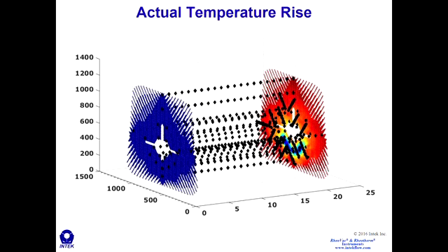And so there are other ways to monitor air binding as well. We've developed another instrument, a temperature string. It's a very small OD string that we thread through individual tubes. The OD of the cable is about 1/8 of an inch, and it gets strung down the length of tubes.